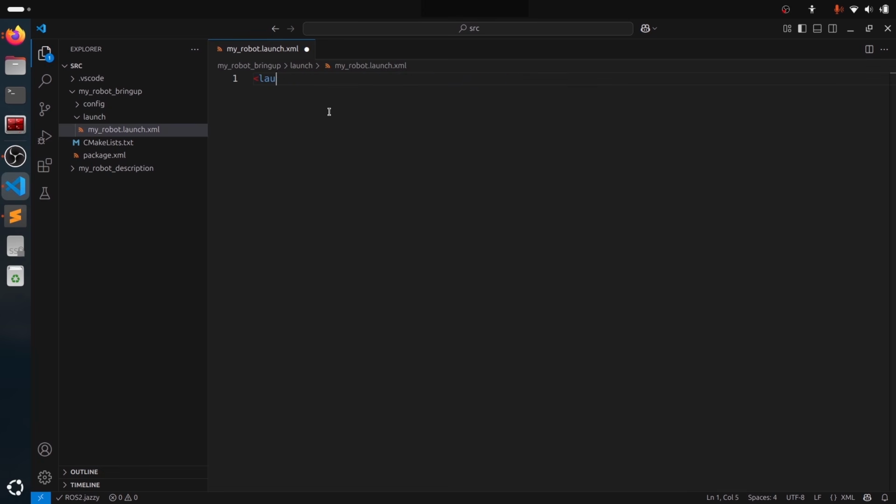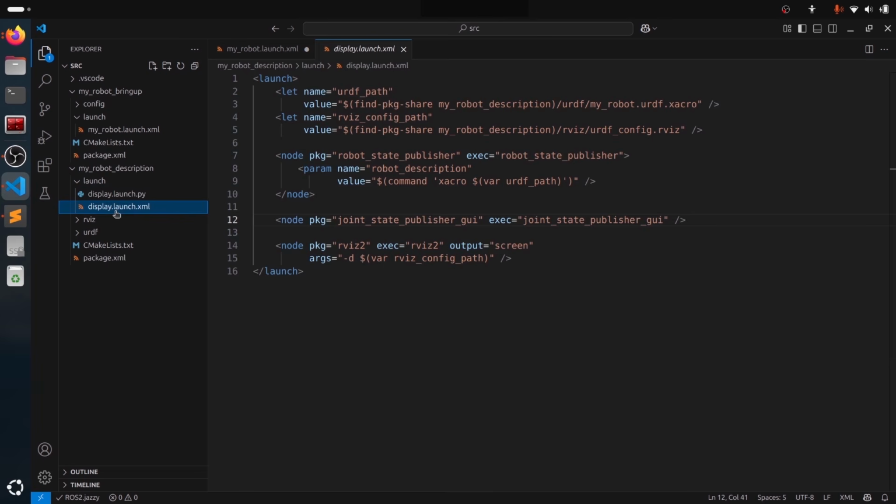Okay, so let's start. We have a launch tag, that's it. And what is the first thing we need to do? Well, we need to start the robot state publisher. And with this, we also need to pass the URDF. Now, the good thing is, I'm not going to reinvent the wheel here. If I go to my_robot_description in my launch file display.launch.xml, that's what we have done actually.